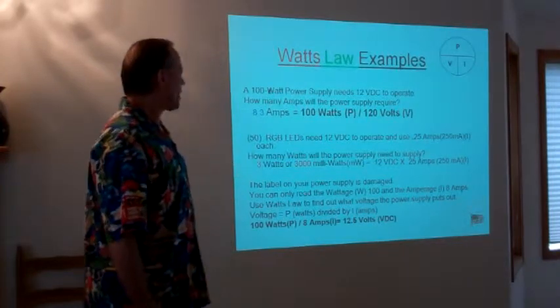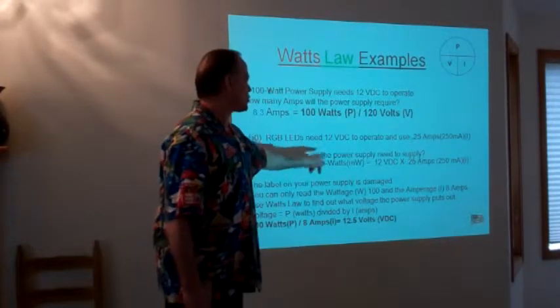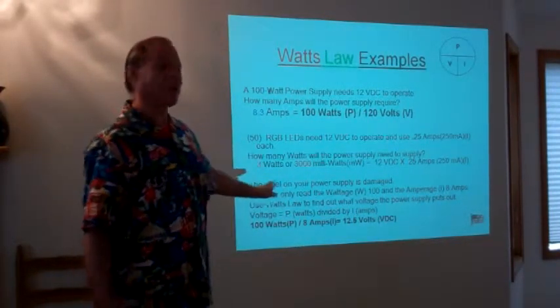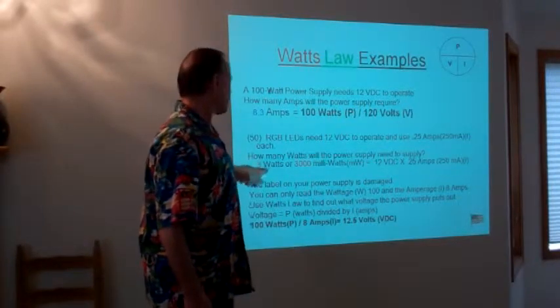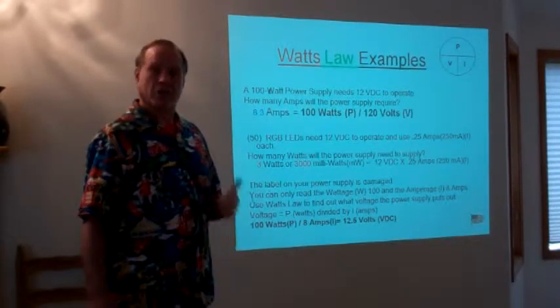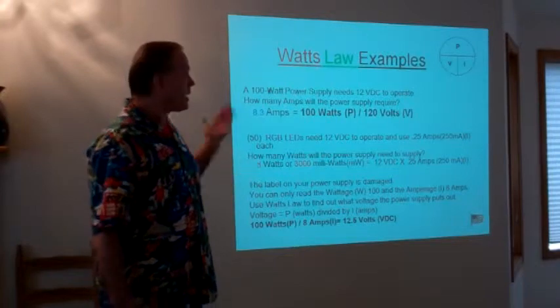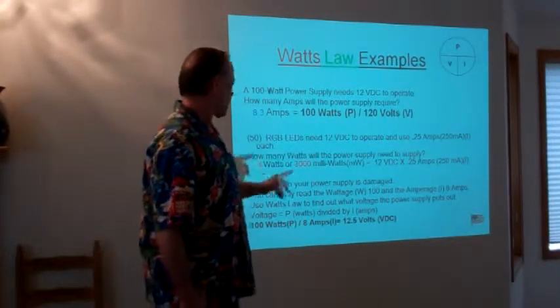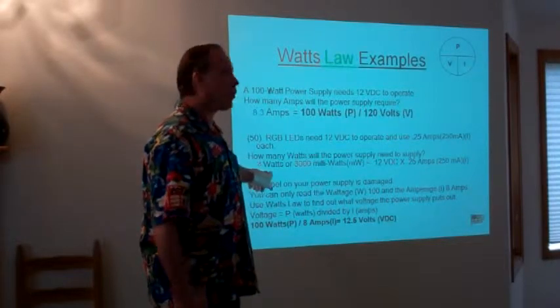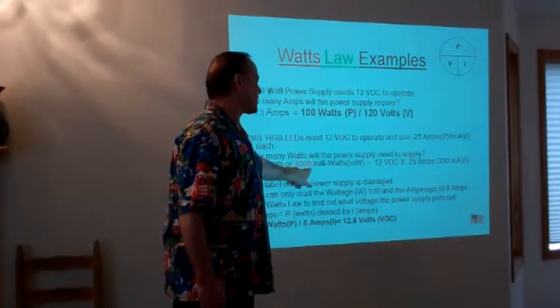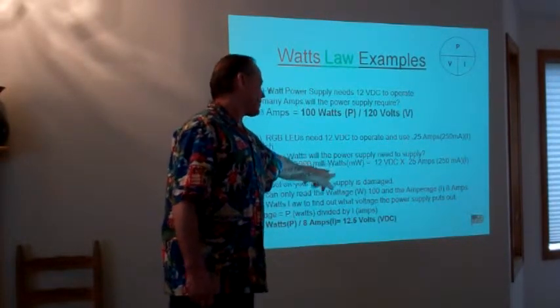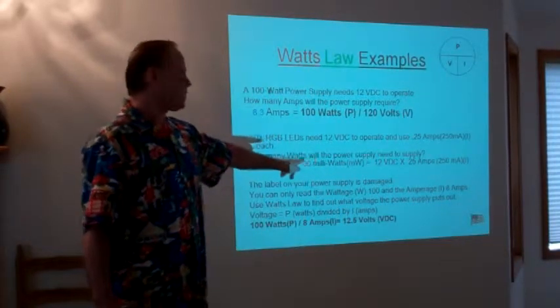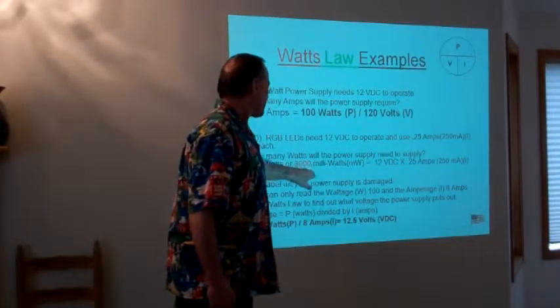Okay, so how many watts will the power supply need to supply? How many watts will it actually supply? Well, if we're looking for watts, we know that's a combination, using volts times amps to get us the power. 3 watts would be the answer, or you might also see it listed as 3,000 milliwatts, or mW. This is not an uncommon way to see it.